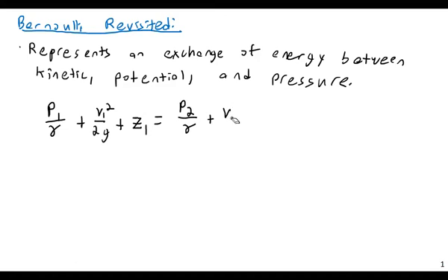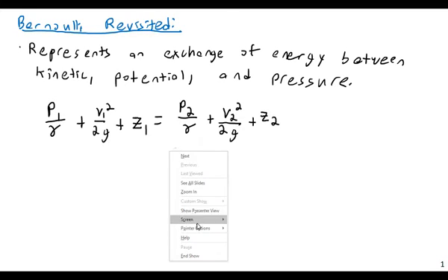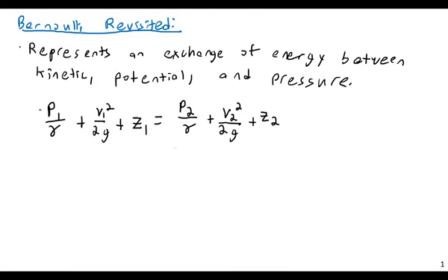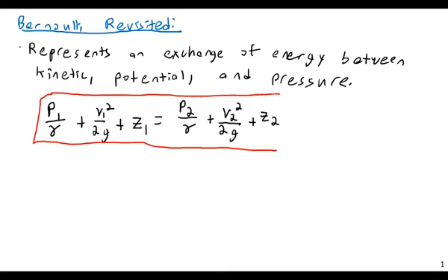You can rewrite this for different forms, optimize it for different quantities, depending on your exact system. In different courses and applications where people use Bernoulli, it's very common to see them rewrite it. Maybe if you're using a system with a lot of pressure units, you'd rewrite it not in terms of height, but in terms of pressure units. If I was optimizing it for pressure, I would have just a P1 here and not a P1 over gamma. This one is optimized for height.